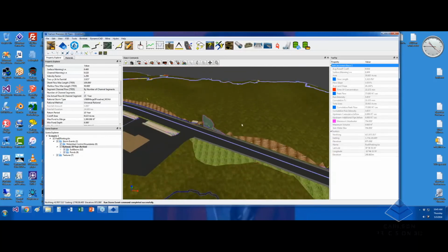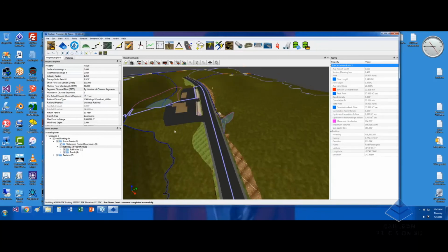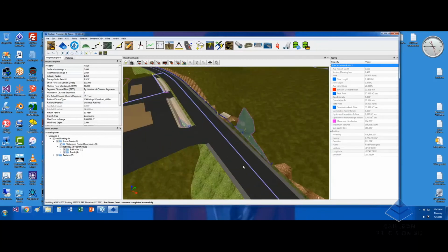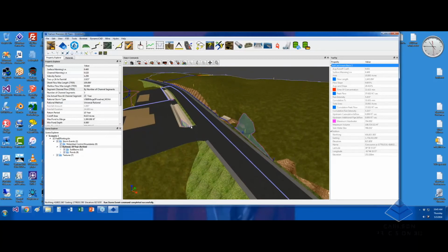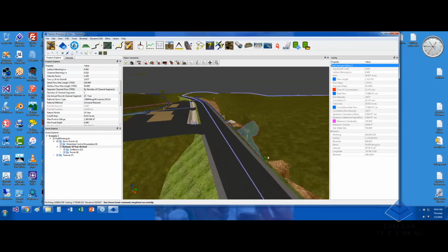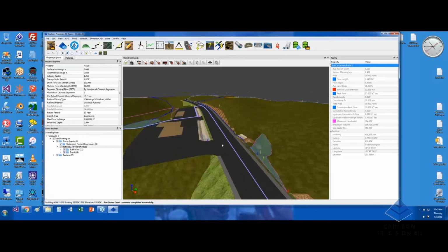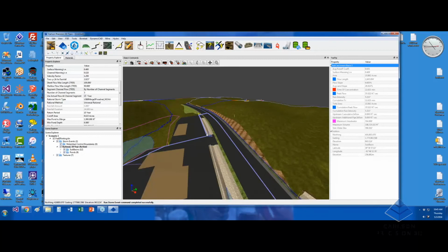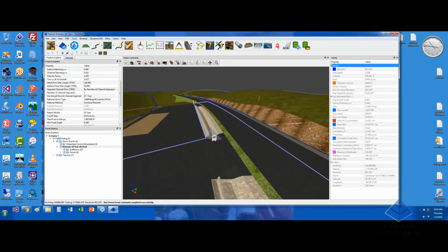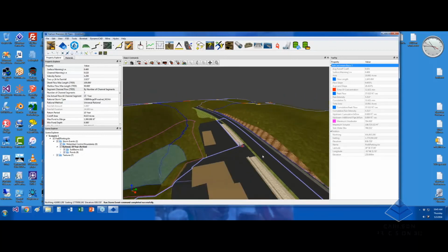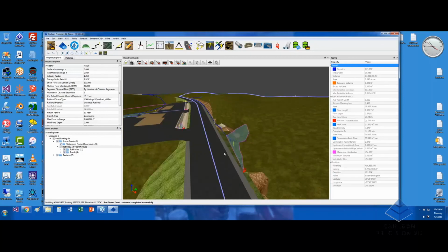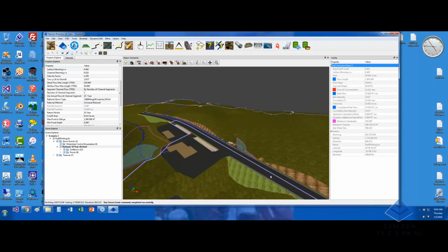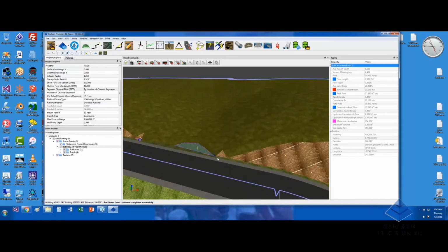So what I'm going to do is use our simple red gate technology. What that means is these blue gates, these are adjoining subbasins logically. I'm just going to double click on them, and I'm going to turn them red. And what red does is red forces the water not to flow in there. So you can toggle them from a distance, but when you see that gate show up, that means they're red gated, meaning we're cutting off the water. We're going to isolate those sections. I'm going to do that one. I'm also going to isolate this one as well.